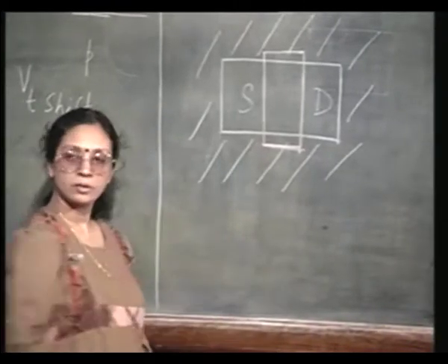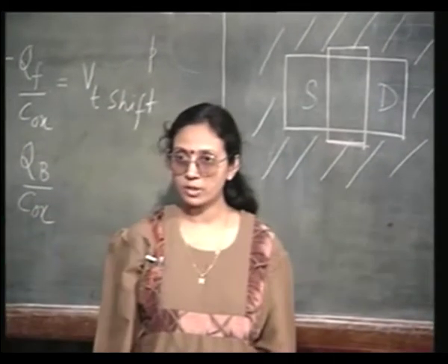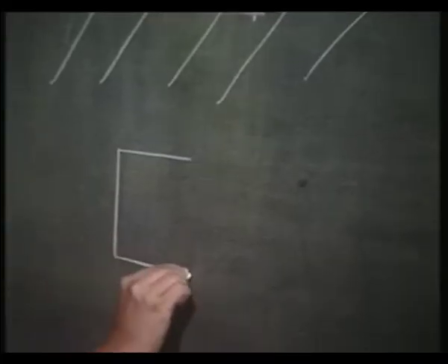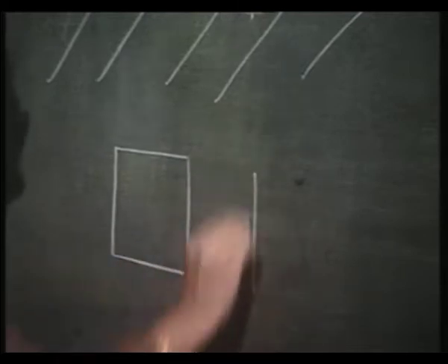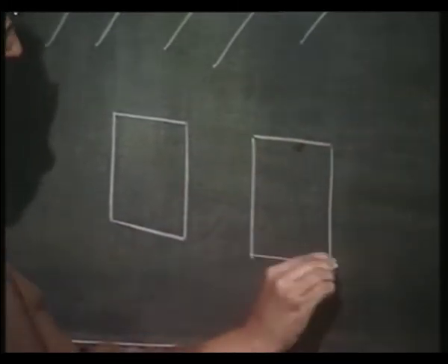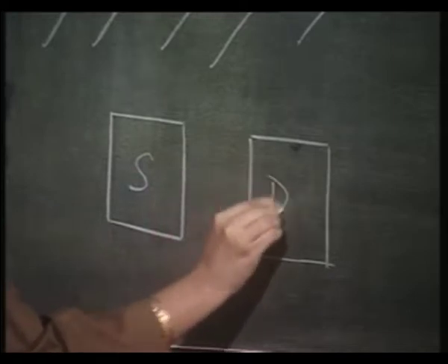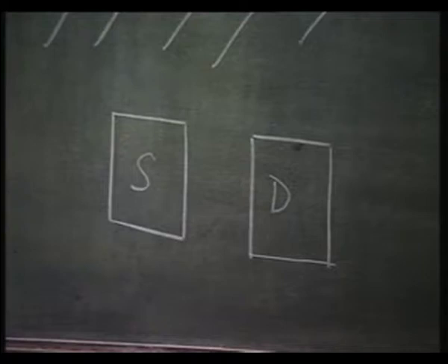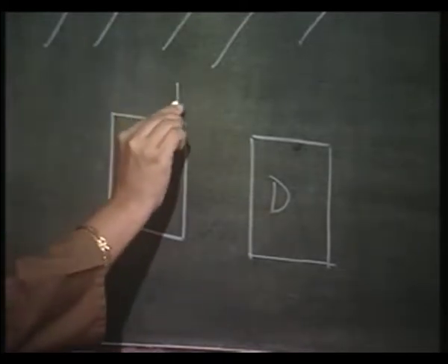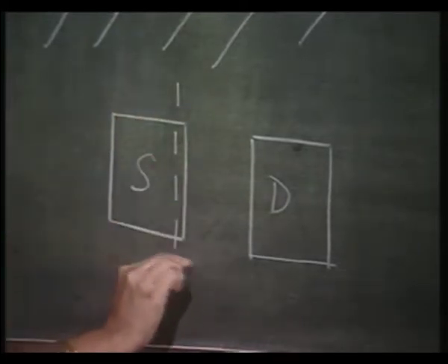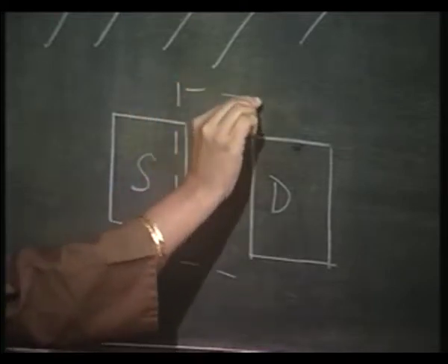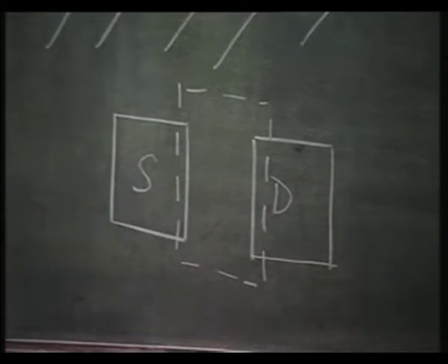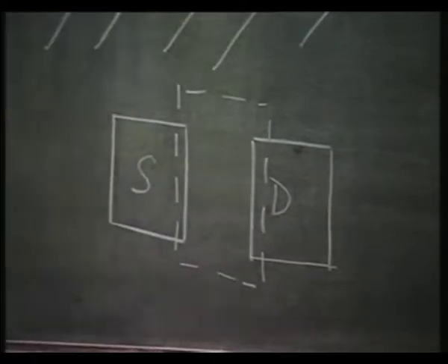We had the first step, we had thick field oxide, then we had opened the source and drain window in that. So, first step was opening the source and drain window, and then after that we had to define the gate. So, what we had to do is to make sure that the gate actually overlaps the source and drain region. Compare it with this.